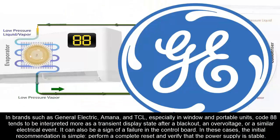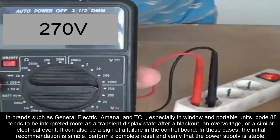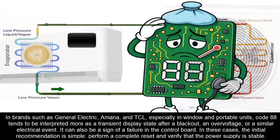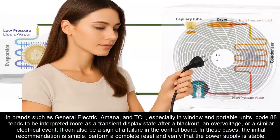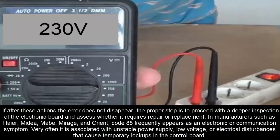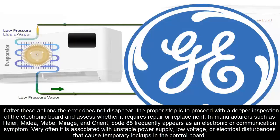In brands such as General Electric, Amana, and TCL, especially in window and portable units, code 88 tends to be interpreted more as a transient display state after a blackout, an overvoltage, or a similar electrical event. It can also be a sign of a failure in the control board. In these cases, the initial recommendation is simple. Perform a complete reset and verify that the power supply is stable. If after these actions the error does not disappear, the proper step is to proceed with a deeper inspection of the electronic board and assess whether it requires repair or replacement.